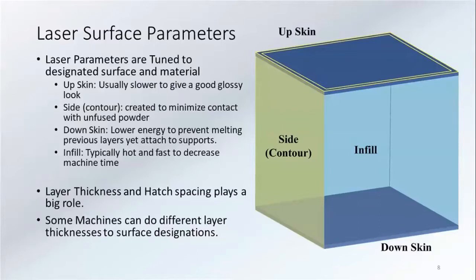Infill is where we're just getting metal down. So we're typically going at a hotter power, we're going faster, and we're trying to save some time because we took the time on the downskin, the sides, the contours, and the upskin. So we're just trying to get things done.